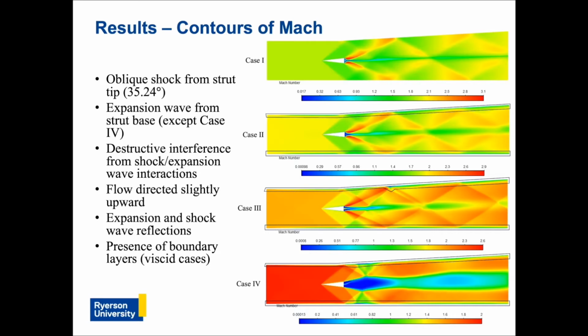A direct comparison can be made between cases 1 and 2, since both have no hydrogen injection, where an extra shock reflection occurs in case 2 near the outlet, accelerating the flow to around Mach 2.15, whereas the inviscid case has an exit Mach of under 2.1 in the peripheries around the central wake region.